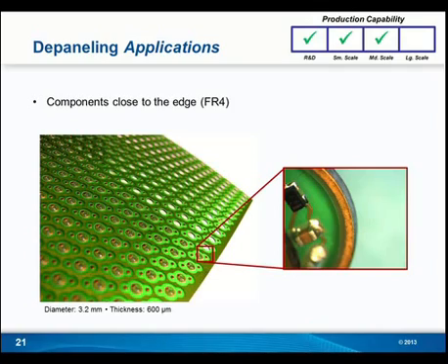Thanks, guys. I wanted to bring our next question up from Jody, which is pretty cool. Can the laser double as an engraver for labeling? Yeah, with a wide variety of materials. If you just need to mark and engrave, the systems allow you to control the settings down and just do a quick mark on the material, the component, the IC, the BGA. If you wanted to put your logo on it, it's all just a function of importing your design data and text, and it can easily structure that text and etch it on different material types.